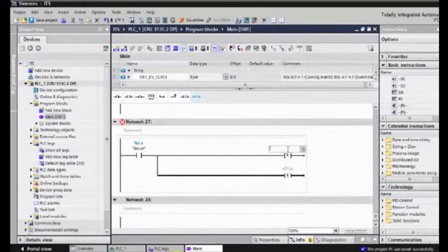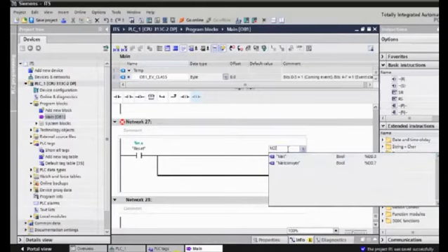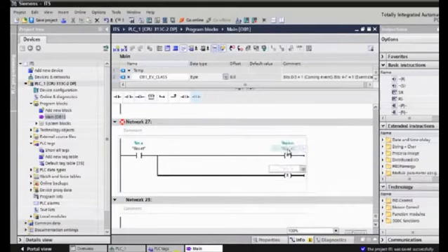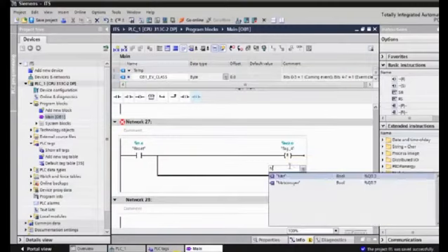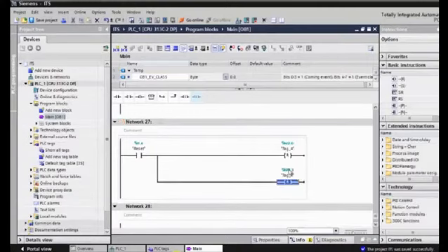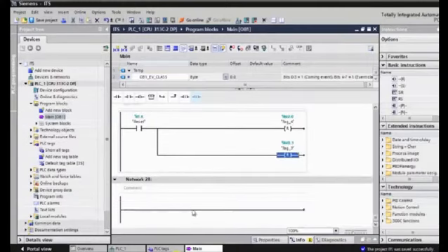At the end, we are going to use the reset button input 1.6 to reset the other markers. First one, M2.0, which is used for the mat, and M0.3. At first, if we are between the up position and down position, we are going to bring the mat down.